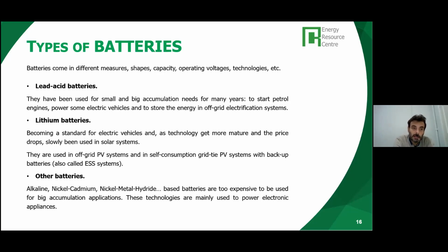But we also have other types of batteries: alkaline, nickel cadmium, nickel metal hydride, batteries that are either too expensive or have issues with the toxicity of the materials. In the case of nickel cadmium, for instance, heavy metals make these batteries not really suitable for solar applications. They are mostly used for power electronics, machinery or products, but not really for solar applications. For solar applications, we mostly concentrate on the lead-acid type of batteries or the lithium-ion.